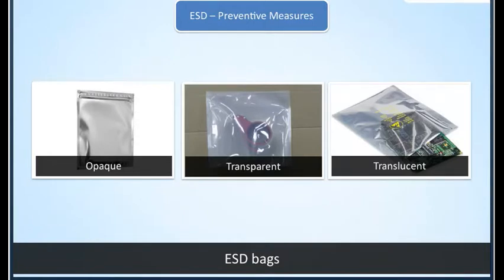Transparent bags can pass ESD charge as high as 600 V to the device inside, depending on external charge level. But they are not very durable and get punctured easily by solder points on the PCB. These bags are recommended for one-time use. The silver translucent bags include a conductive nickel or aluminum layer and offer an anti-static enclosure along with a conductive shield for induced charges. These bags are more durable and the most preferred ones.